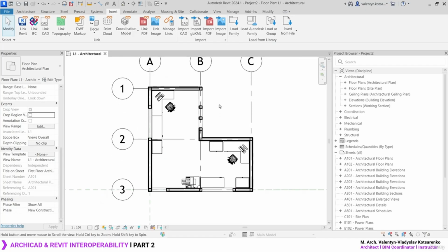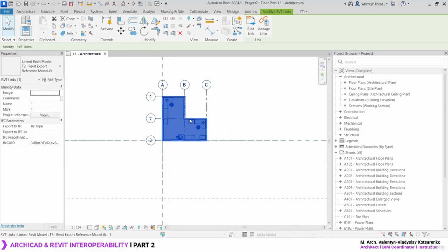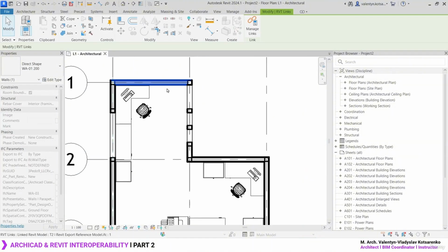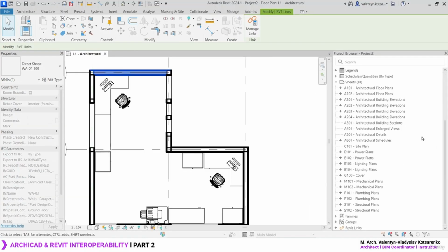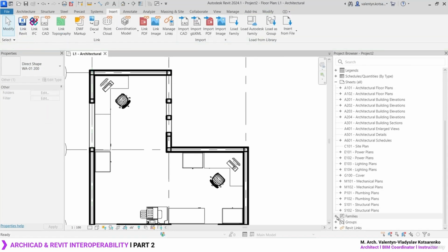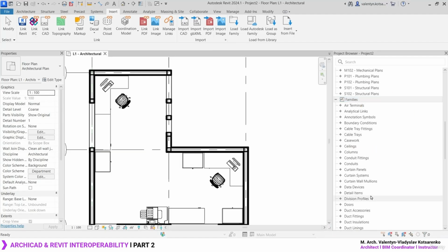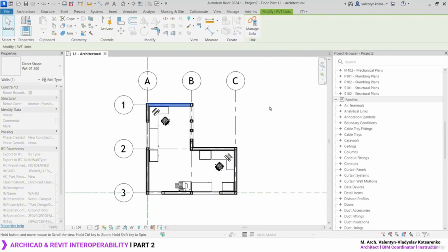So you can instantly notice that you get the grids. That's quite useful. If you select the model, it's going to select the whole element unless you press the Tab key, and then you can select individual elements. But the thing here is that this is still a direct shape. The same will happen. You won't get the possibility to, for example, visualize everything divided and organized by families. So it's going to represent some issue. If you notice from the previous model, you got some type of polygons looking over here, which is some type of issue. Maybe for documentation, that's going to be a problem.